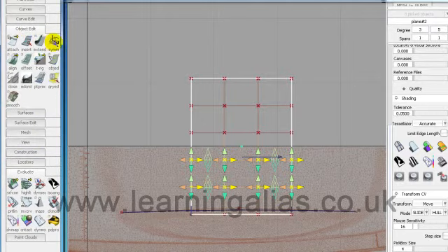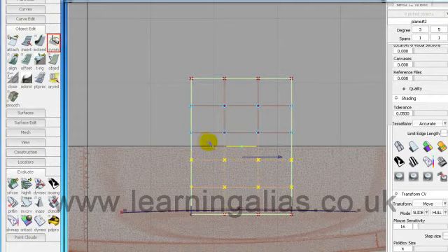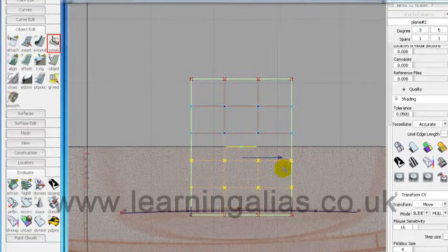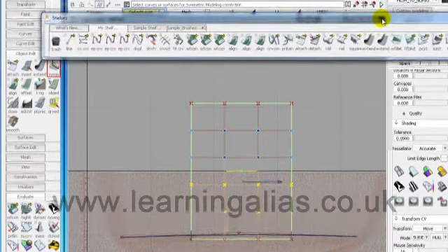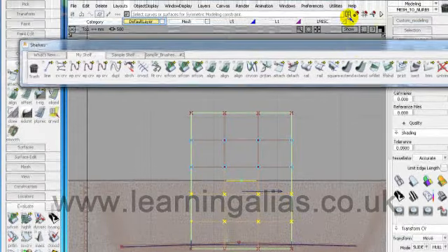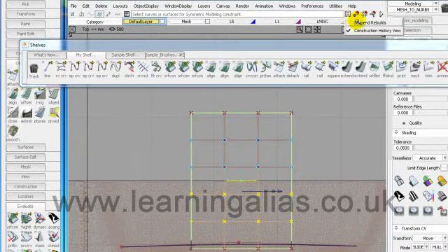So it's Object Edit, Symmetrical Modelling. Make sure you've got that plane there showing you that you're in symmetrical modelling mode and these little blue circles here. I'll show you something now that we're going to be doing a lot in this video. We're going to come up here to History and Suspend Rebuilds.